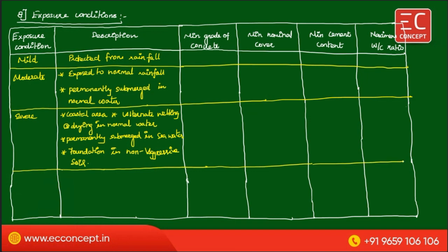Again, after severe comes very severe. In the very severe condition, the structure is subjected to sea spray, alternate wetting and drying in sea water, and foundation in aggressive soil.